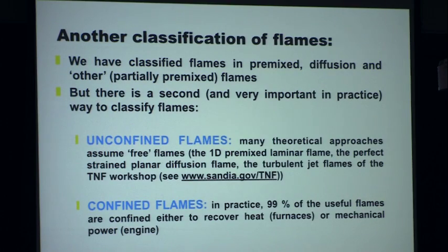Okay, I want to go now to another definition of the flames we're going to face. This one is based on the confinement problem, on the geometrical problem. We can basically split flames in two big categories: unconfined flames and confined flames. Unconfined flames, as you would expect, is a flame in a free space. There's nothing going on, there's no wall. You don't have to worry about the shape of the chamber or anything. And confined flames, it's much more complicated because you need to take into account the fact that the flame is taking place in a geometry with walls everywhere.